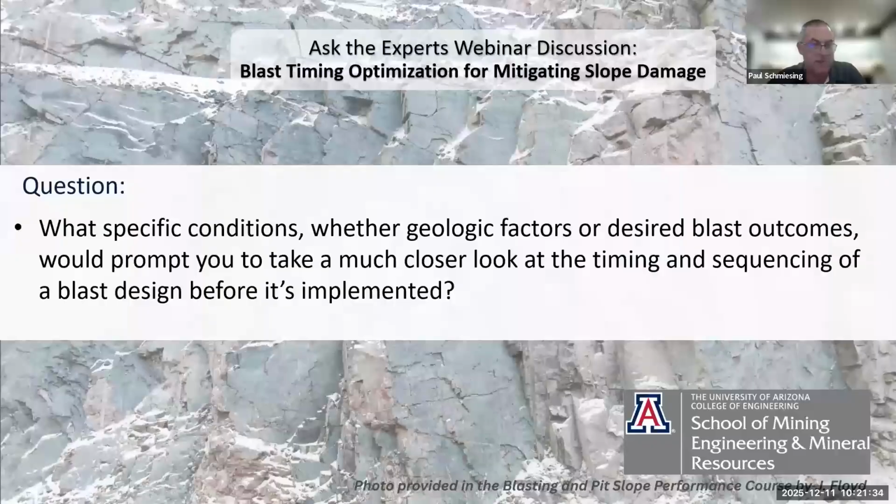The other big thing that we've been doing is, when assessing how our blasts are doing, we're using seismographs. One of the things that we can pick up from that is, hey, the timing was working really good through the first third of the shot. Next third of the shot, okay, the vibration's really high. Next third, it's back down to normal. So when we look at it, it gives us, okay, what's going on in the middle?